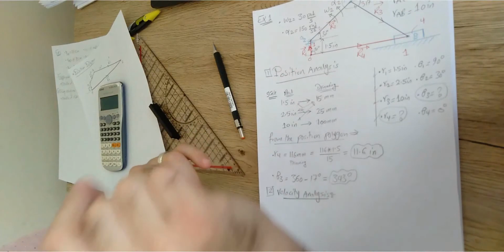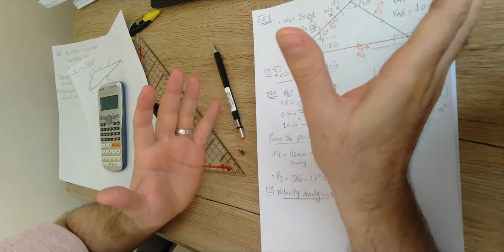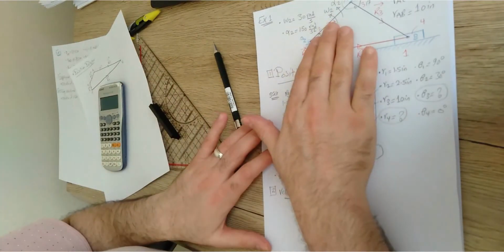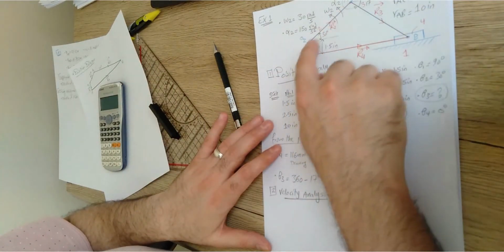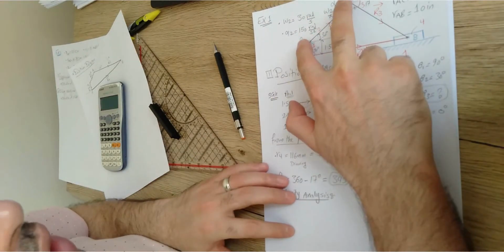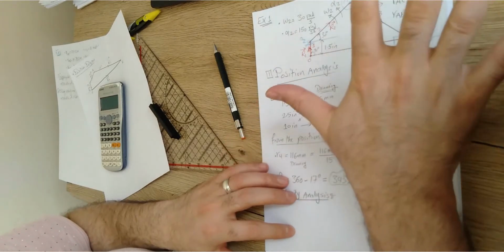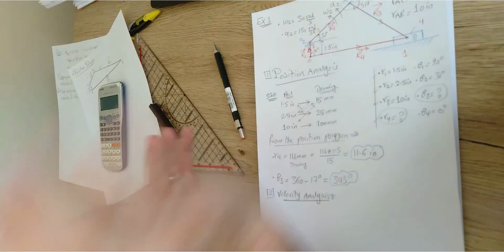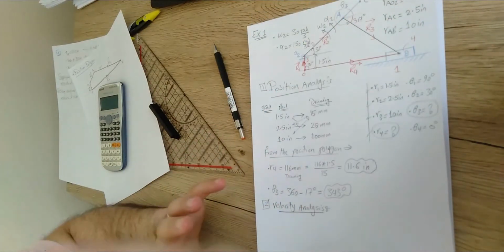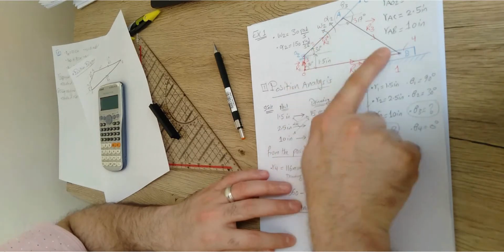First of all, we have to start from the link with the given information regarding the velocity. Now we are working on the velocity. All the velocity data are given for link O2A, which is link 2, or position vector 2, right? So link 2 is the link that I'm gonna start with. Then keep going till you finish the other links or elements within the mechanism. Generally, we have in this mechanism 3 objects: link 2, link 3, and the slider.